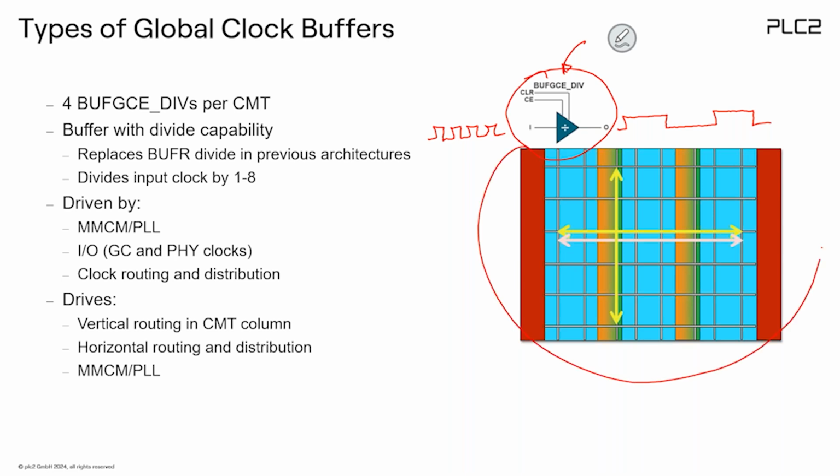And what you see here, this picture, basically shows the layout of the FPGA. These are the regions, the simple clock regions, and the buffers are always contained in this column. So this is the column, and the buffer may be routed to all of the regions. For the UltraScale, there are virtually hundreds of clock buffers and clock regions available. For the 7 series, we have 32 clock buffers available.